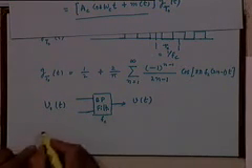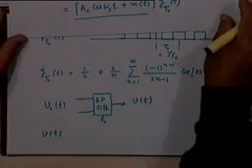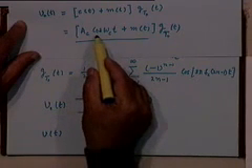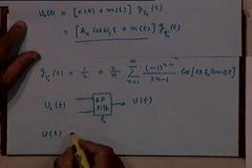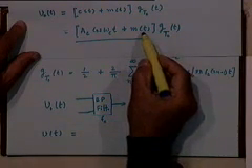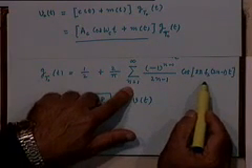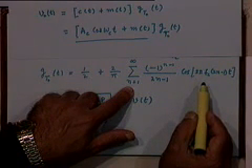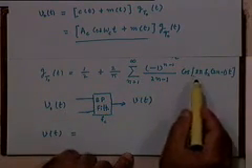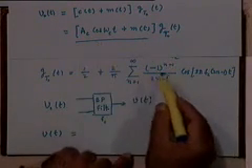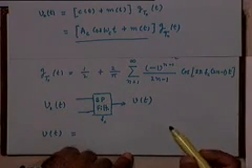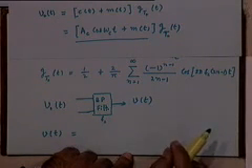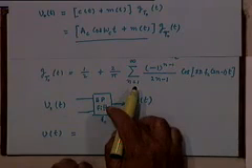So the output v(t) in this case would be, look at the product terms which will be at frequency f_c. There is this constant half which will multiply with A_c cosine omega_c t, right, and there is this message m(t) which when multiplied with the first term of the Fourier series will produce a component at or around omega_c, right. All other components in this term when multiplied with either this or this would lead to frequency components which are multiples of omega_c, right, 2 omega_c, 3 omega_c, whatever, and they will all be rejected by this band pass filter.